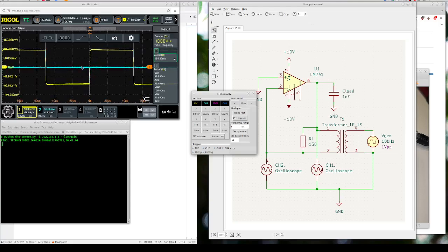So this is how it looks. The signal is a bit smaller than before. The amplitude is apparently 180 millivolt. That doesn't really matter. It's still averaging, so the setup is the same, except you see the blue one is actually almost constant, the signal, because that's compensated by the loop gain.